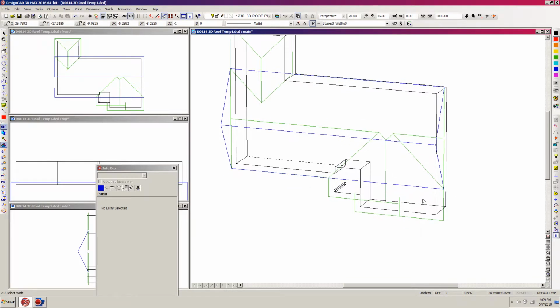And so first and foremost, I'm going to start with a plane for this secondary gable here. And in order to do that, I'm just going to hit P for plane and right click here and just bring it on up a ways. H for orthogonal mode on up, the height doesn't matter. I just want to get past the main ridge there and set a point. And H to go out of orthogonal mode. And now gravity move and I'm at zeros there.